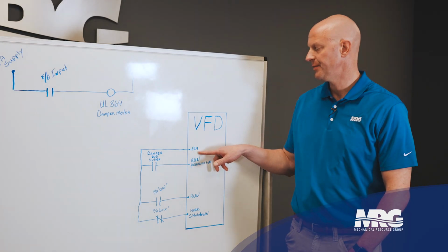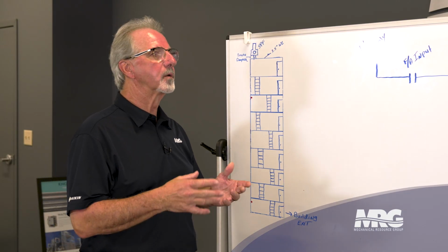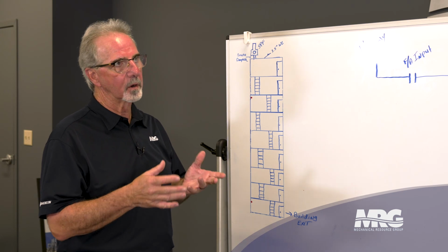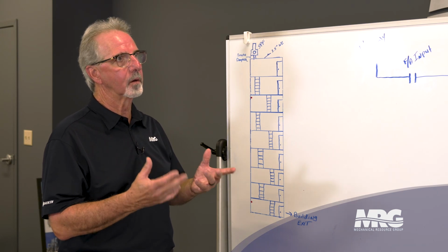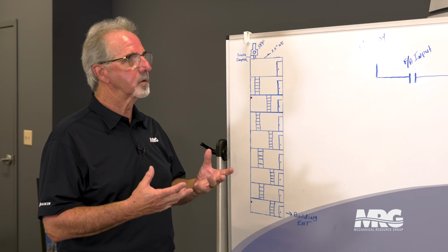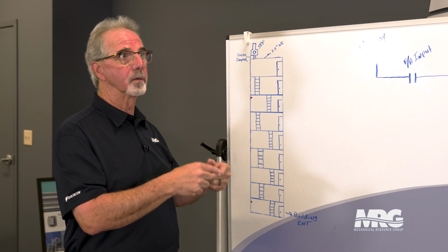So you have P24 noted here. Yeah, what that is, the low voltage that's generated by the drive. Now, obviously the drives in stairwell pressurization, generally they're going to be a bypass drive. And so I rely on my low voltage control, and I pass that to the fire alarm, and then fire alarm brings it back to me.